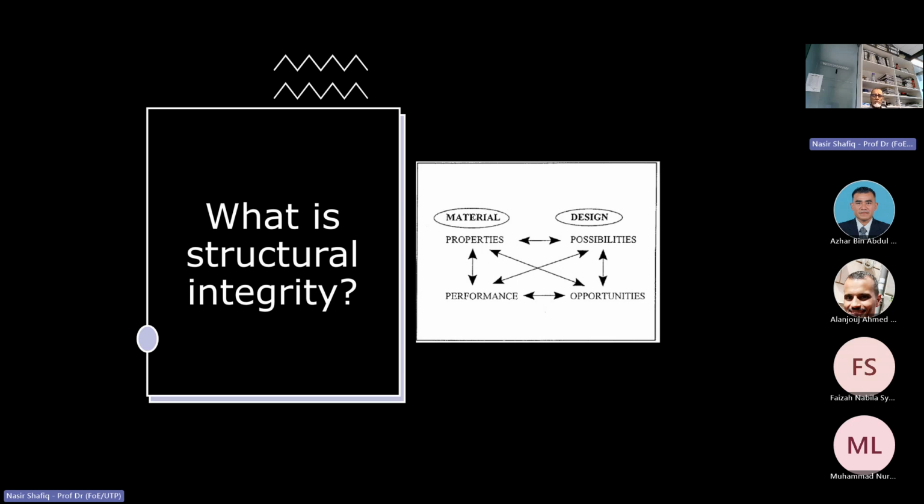This gas, which will be forcing at 200 bar or 20 megapascal, will apply pressure on the pipe wall thickness, and using the relevant design formula like the API formula, you come up with the hoop stresses or tangential stresses. So you come up with the pipeline thickness of 20 mm.